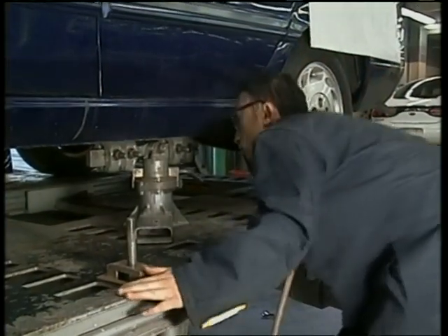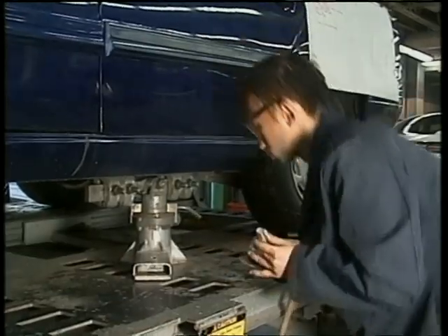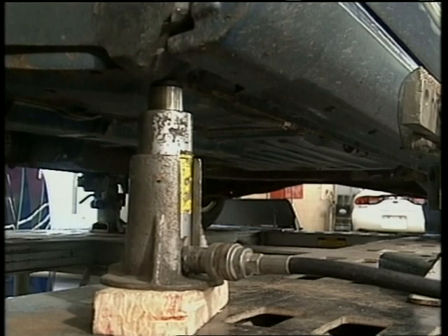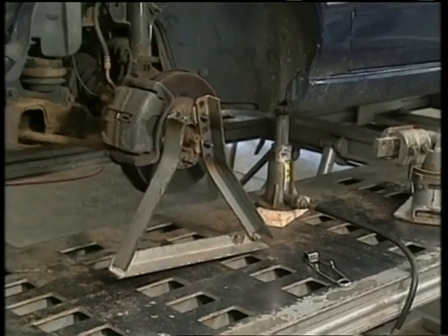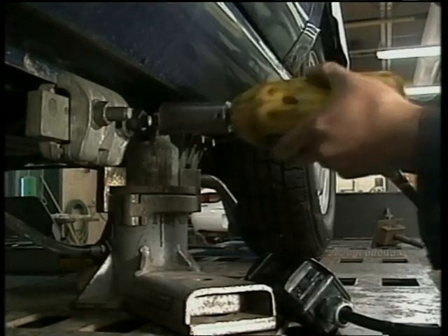Always anchor the vehicle securely before making a pull and check that the clamps and bolts are tightened. Use the proper size and grade of chain. Never use a service jack for supporting a vehicle. Always use jack stands. Always make sure that rocker panel pinch welds and chassis clamp teeth are tight.